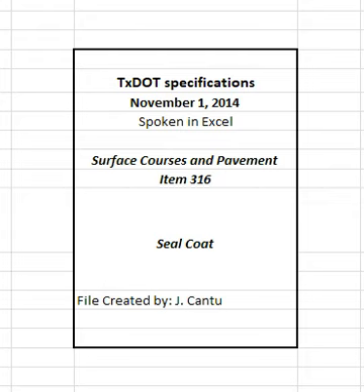3.1.4 Computerized distributor. When paying for asphalt material by weight, the engineer may allow use of the computerized distributor display to verify application rates. Verify application rate accuracy at a frequency acceptable to the engineer. 3.2 Aggregate spreader. Use a continuous feed, self-propelled spreader to apply aggregate uniformly at the specified rate or as directed. If racked-in aggregate is specified on the plans, furnish a second aggregate spreader for the racked-in aggregate to apply aggregate uniformly at the specified rate.